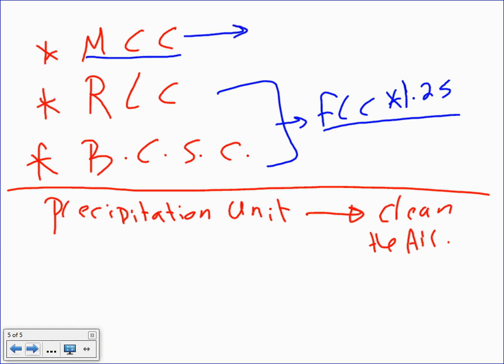On this side, it's clean air. So who cares, for me as an electrical engineer and you guys as electrical designers? We need to power this piece of equipment. How do we power it? What's in it? It's a motor. How do we power a motor? 125 percent of the full load current of the equipment, 250 percent of the full load current for the overcurrent protection device, 115 percent for the disconnect. What type of controller do they want? Minimum magnetic starter, done.